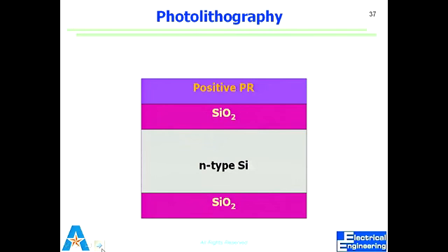So what we do is we apply this photoresist, and we spin it for a certain time at a certain RPM. This results in a certain thickness of resist. And now I take it from that chuck and put it into a machine I call a aligner. An aligner essentially has a slot where I put the mask. It has a light source at a certain wavelength, and that wavelength is something this resist is very sensitive to.